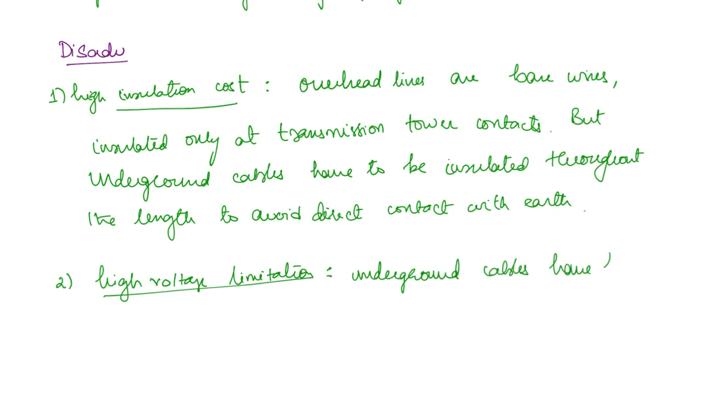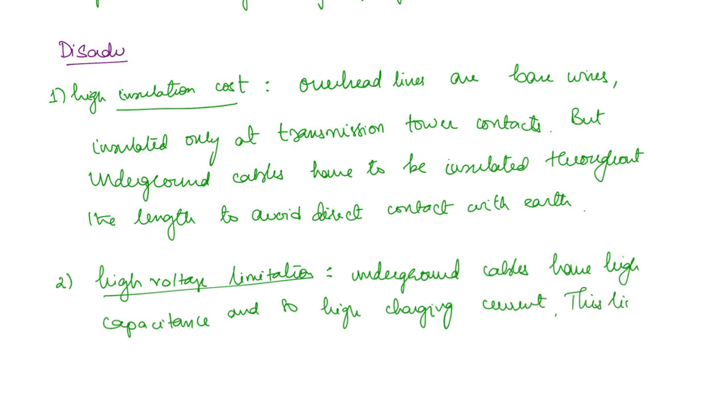Okay, so underground cables have high capacitance and so high charging current. This limits the use of cables for high voltage levels.